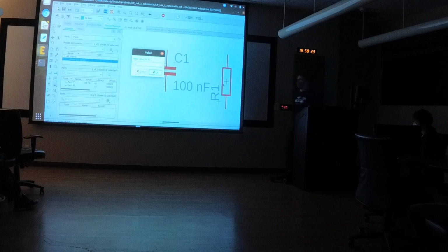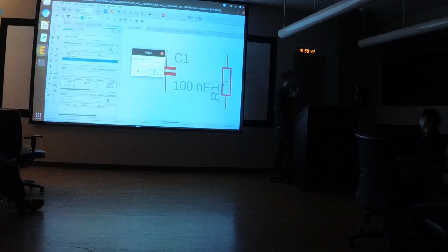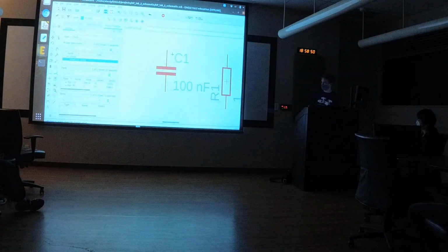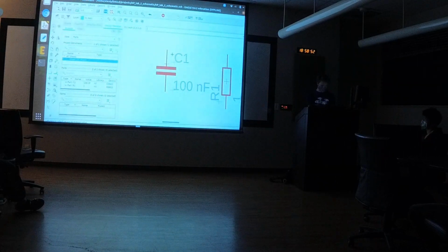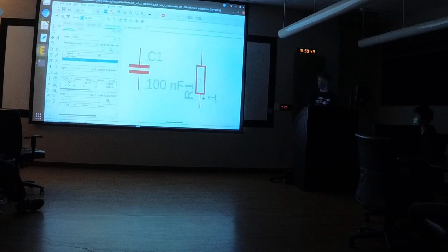So just a little bit of at least how I do stuff. For resistors, I don't type in ohm afterwards. For capacitors and inductors, I use either F or H in order to be able to tell stuff apart. For resistors, there's no ohm symbol, so I just leave it blank. If you wanted to do nano or thousands, you just write K or N after it. Like if you want a 10K ohm resistor, you just write 10K. You don't have to write down 10,000.